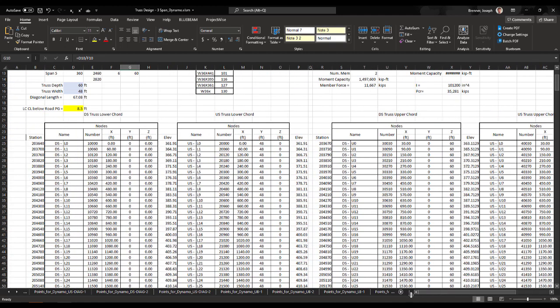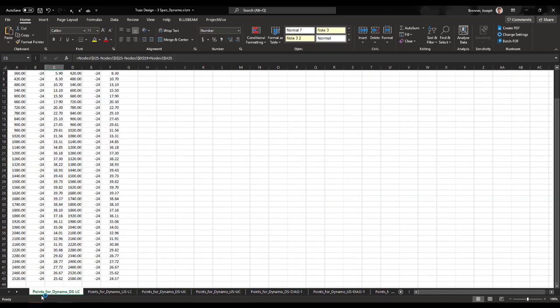So we're taking that information, and we're pulling that out into our specific needs for geometry for our members. Again, it's all already produced, all the points are there. We just need to update it. And the other thing we're doing is bringing in our Civil 3D or our roadway information, and through our targets, we're able to find specific elevations that we need to hit for vertical curve.